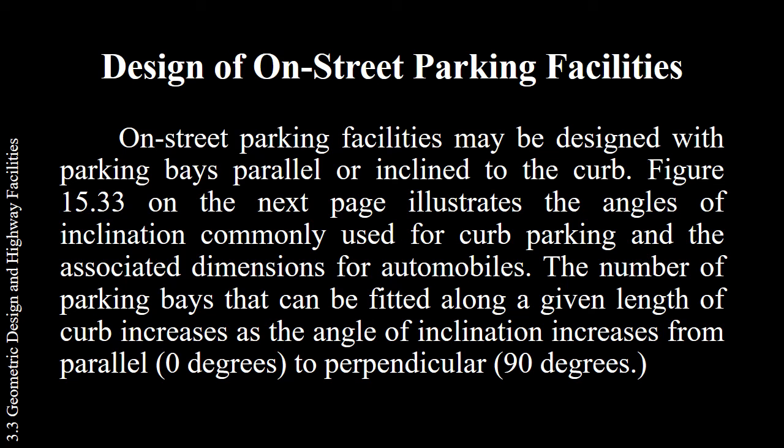Design of on-street parking facilities. On-street parking facilities may be designed with parking bays parallel and inclined to the curb. Figure 15.33 on the next page illustrates the angles of inclination commonly used for curb parking and the associated dimensions for automobiles. The number of parking bays that can be fitted along a given length of curb increases as the angle of inclination increases.